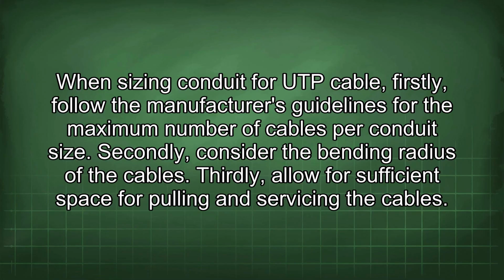When sizing conduit for a UTP cable, firstly, follow the manufacturer's guidelines for the maximum number of cables per conduit size. Secondly, consider the bending radius of the cables. Thirdly, allow for sufficient space for pulling and servicing the cables.